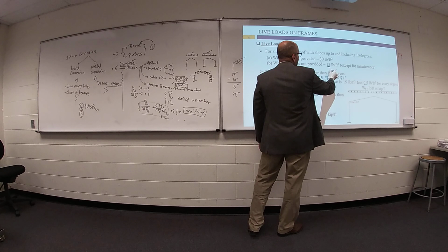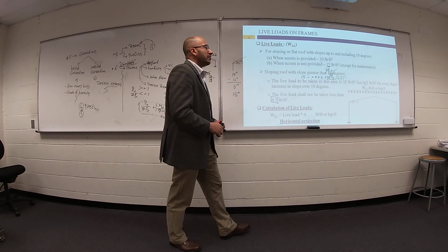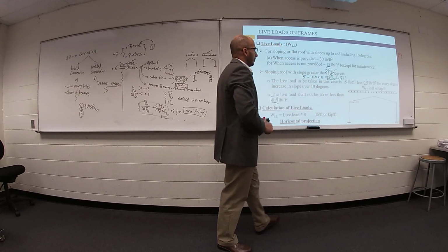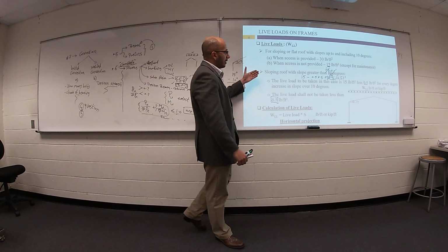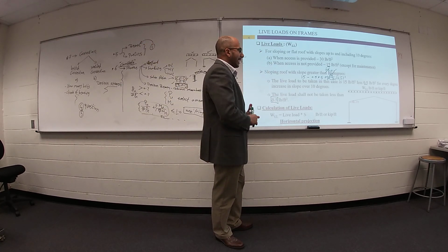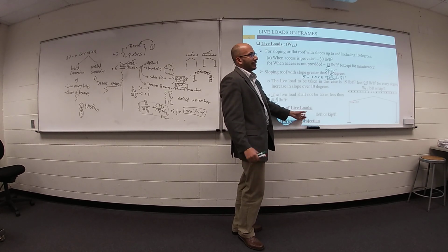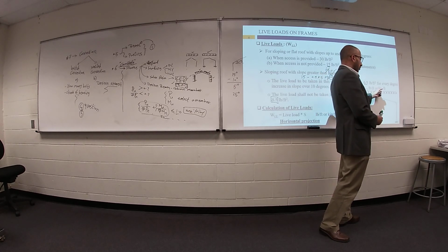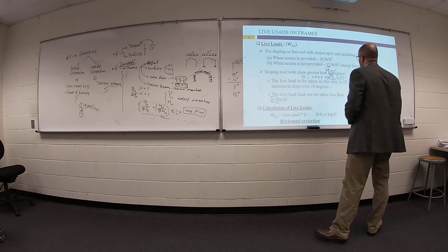If you have something here equal 3.5, no, go ahead and use 8.5. So this value must be 8.5 or greater. Then your live load, which is pound per unit area, go ahead and multiply this value by S, spacing between each main system, you can get your live load horizontal projection.